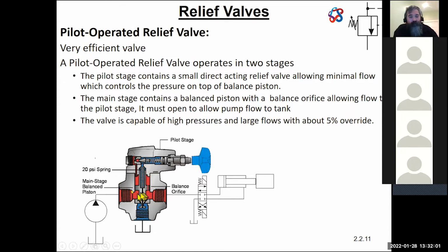So what happens as the pressure starts to increase? I've got a pilot stage, and let's say it's set to 1,000 psi, just to make it the same as what we were talking about earlier. I've adjusted this to 1,000. I've got no idea what's happening internally; I just know I've got it set to 1,000 psi. So what's really going to happen is this spring is now set to open at 980 psi. From outside, it just looks like 1,000, but it's actually going to crack at about 980. So when it cracks, it allows a little bit of fluid to move past this poppet.